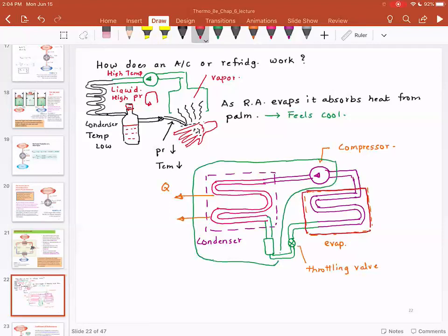And this is actually your system where you should be focusing to cool things down. So the evaporator is inside your house with an air handler. The throttling valve is typically inside the house near the air handler, but the big boxes that you see outside have a compressor, a condenser, and the fan that circulates the air around the compressor and condenser to cool them down.